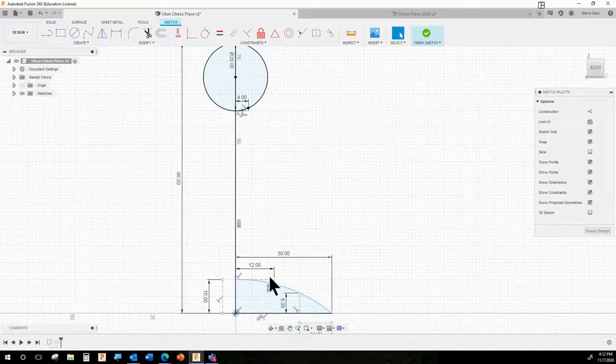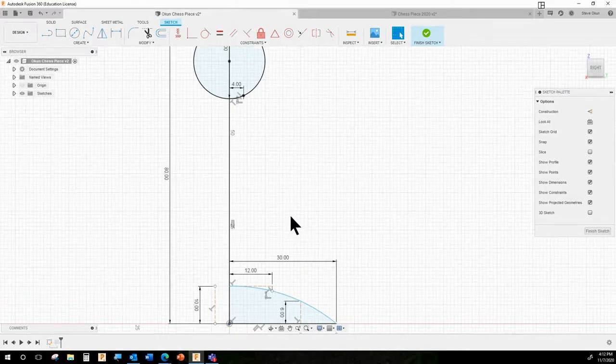And actually, if I wanted to waste your time, I should probably delete all those construction lines. Well, no, those construction lines are still relevant. The client still wants it to connect up here and down there, but the client wants it to come out, like to form a little shoulder and then to come back and form a little body. Okay, so the client has given me working drawings, and the working drawings tell me that the client wants the shoulder to be formed at 45 millimeters high and 20 millimeters out from the central axis.